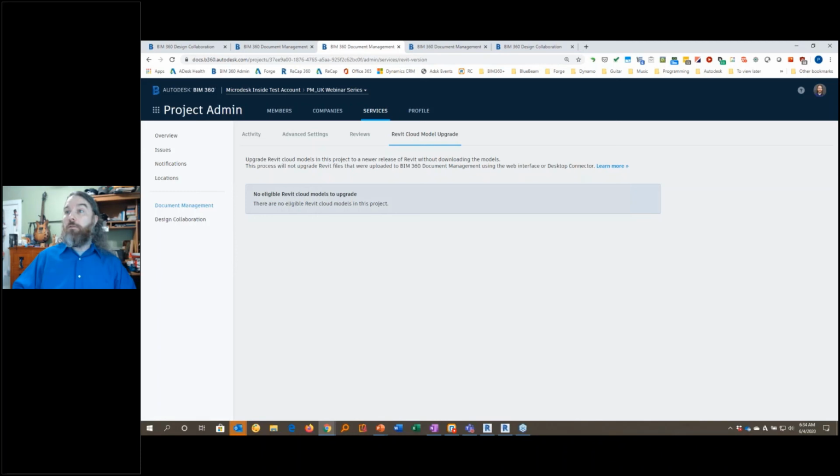Okay. A couple of questions here. Will Civil 3D work with Revit in the cloud? Depends on what you mean by work with. So you can link back and forth. You can have a Revit model that is pulling in the background from Civil 3D. You can be exporting from Revit into Civil 3D the coordinates with the plugins from Autodesk. There's a couple of tools that help coordinate your coordinates and information like that.